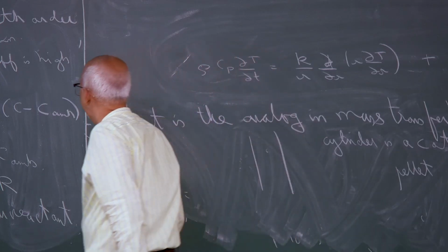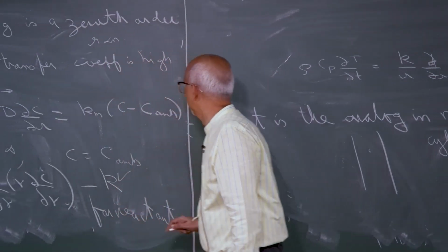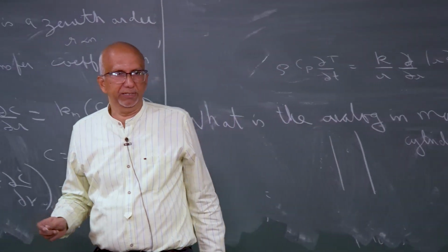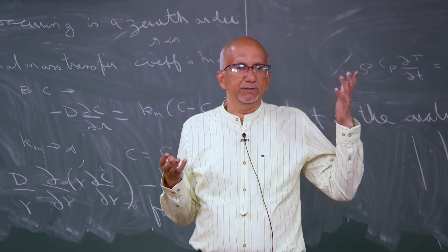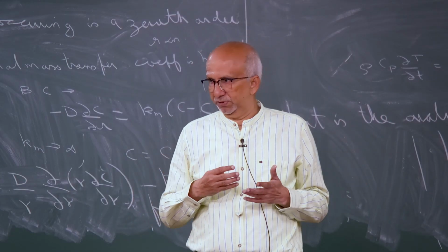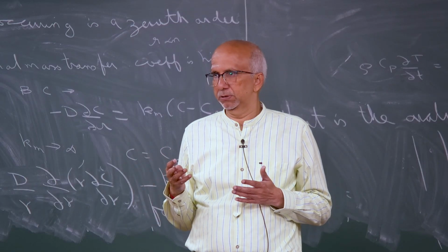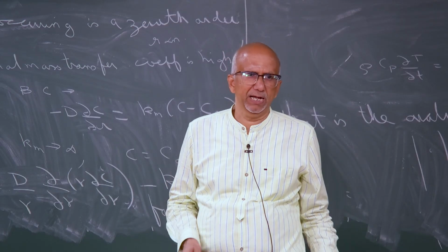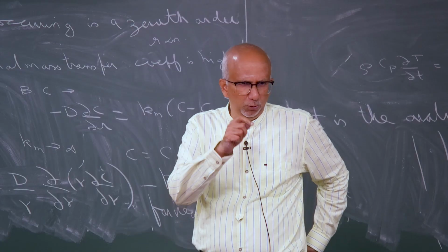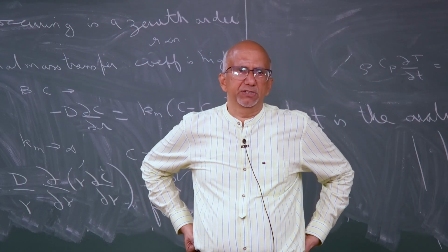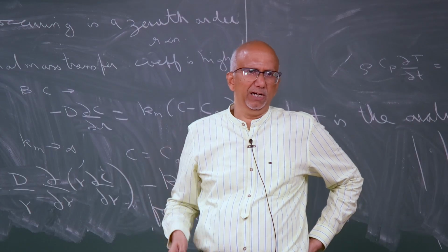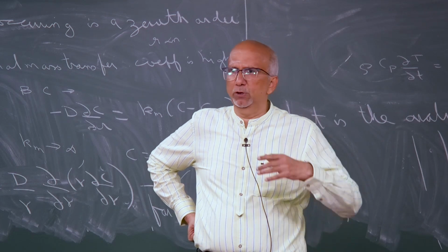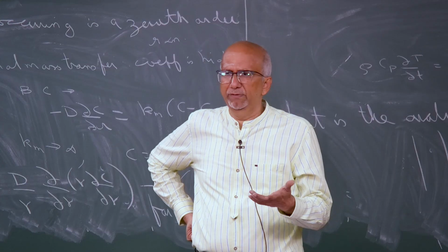So you have a non-homogeneity, this is a non-homogeneity, this again is a non-homogeneity, and you have some initial conditions and boundary conditions. Boundary condition I made the same as u equal to 0 by assuming heat transfer coefficient is large, mass transfer coefficient is large. So boundary condition became the same, and I told you can do some tricks like T minus T ambient to make it homogeneous. So you should be able to basically use the same methods as before. Okay. So this is the analogy which you have to understand, so that you can feel equipped to solve problems. So you don't have to think of new methods for every problem. Okay.